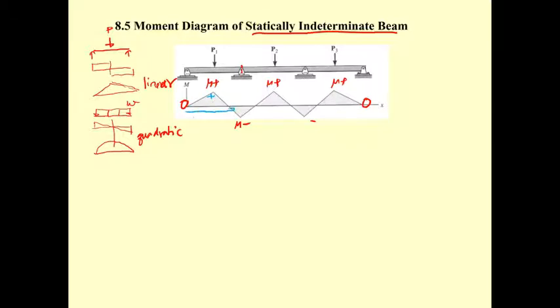So when it's plus, this one is going to be put in this one. If you have the beam like this, and this is going to be the column sometimes, this is the end of the beam, this is going to be put something like this. You have to put some beyond the inflection point to make the development length like this.